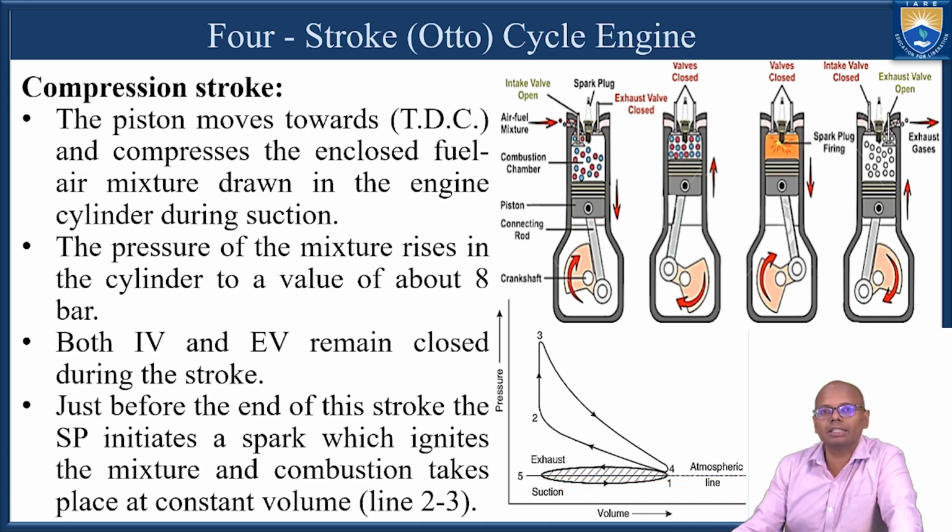So the next one is the compression stroke. The compression stroke means the piston moves from BDC towards the TDC. If the piston moves from the BDC, bottom dead center, to the top dead center, then during this stroke both the inlet valve and the exhaust valve remain closed.